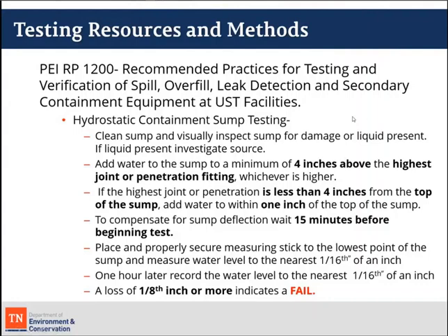You're not taking a ruler, sticking it down there, saying, okay, it's 25.5 inches, we'll come back and stick that measuring stick back in the same place an hour later. Their method actually shows you're leaving that measuring stick in the sump for the duration of the test. You wait an hour, and then you measure to the nearest 1/16 of an inch again.